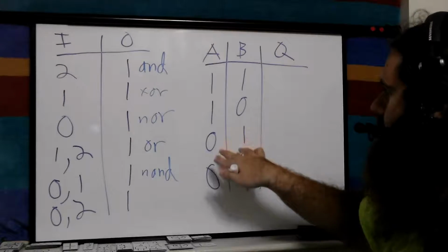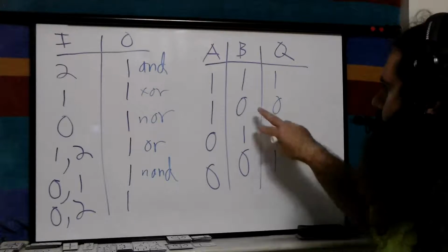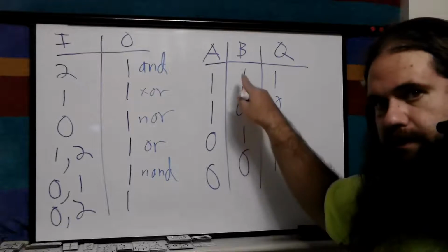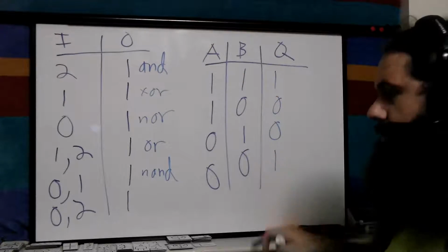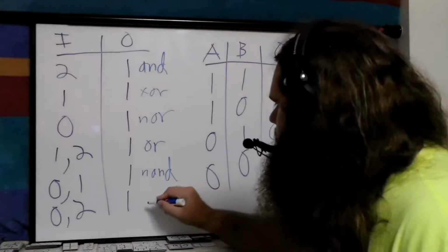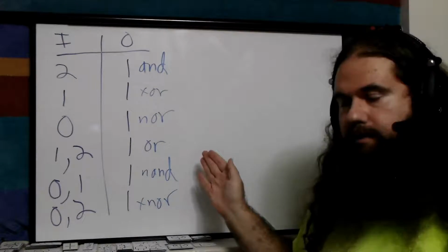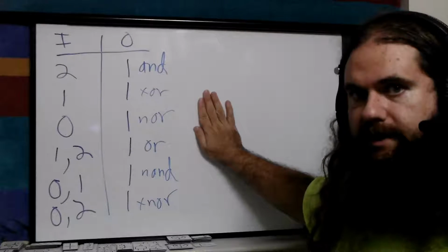And finally, our XNOR. Our XOR was 1 if they were different, but now it's 0. Remember before? It's one or the other but not both is true, but now we flip it to be false. So if there's 2 or 0 ones, we get a 1. 2 or 0, XNOR. And there you go. So now we've proven we can do anything with these 6 gates.